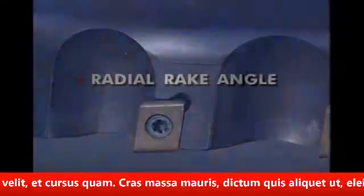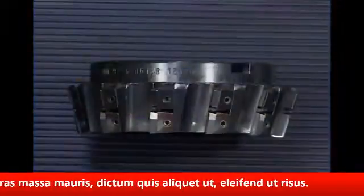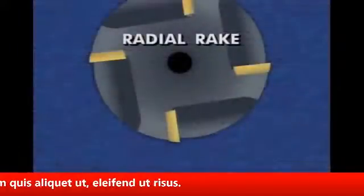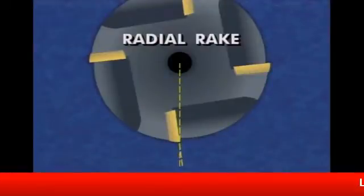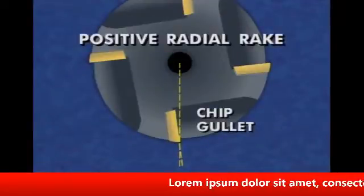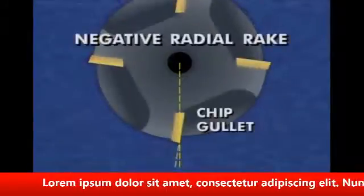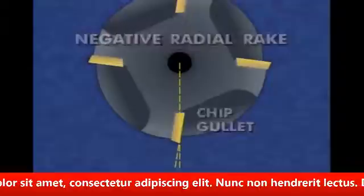Two rake angles, the radial rake and the axial rake, are determined by the position of the insert pockets in the cutter body. The radial rake is the angle measured between the insert face and a radial line drawn from the cutter axis to the cutting edge, hence the name radial rake. If the insert tilts toward the chip gullet, it has a positive radial rake. If the insert tilts away from the chip gullet, it has a negative radial rake.